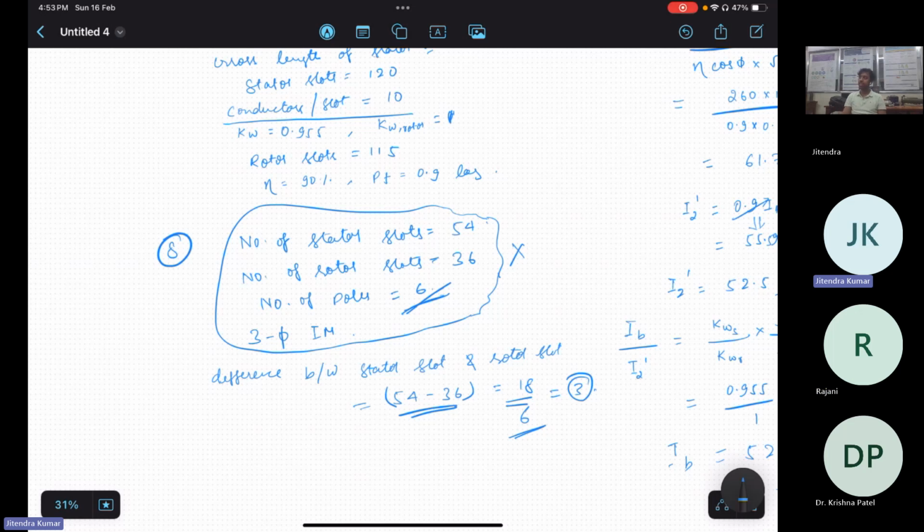So you can also provide some insight to us if you are designing something. Yes, we can. You are aware of MotorCAD, Maxwell and Flux? Yes, all three software. Initially, we go for the MotorCAD. Once we finalize in MotorCAD, we go for the Maxwell and next Flux, Altair software. Okay, so you validate in all three softwares. Right. Nice approach.